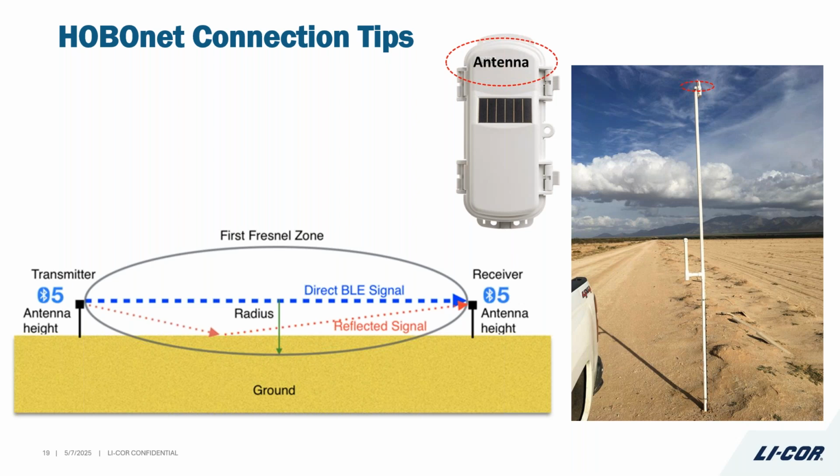and then before you go out and deploy these, come up with an installation plan. Practice on one in your office or at your home base. Set one of these up first, and then go out in the field and install these. And you want to protect your wires from any critters that are out there. We've had a lot of people over the years that for some reason, rodents like to bite wires, so you want to hide all of your wires.